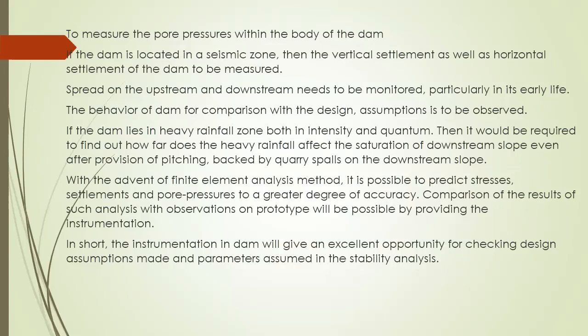With the advent of the finite element analysis method, it is possible to predict stresses, settlements and pore pressures to a greater degree of accuracy. Comparison of the results of such analysis with observations on the prototype will be possible by providing the instrumentation. In short, the instrumentation in a dam will give an excellent opportunity for checking design assumptions made and parameters assumed in the stability analysis.